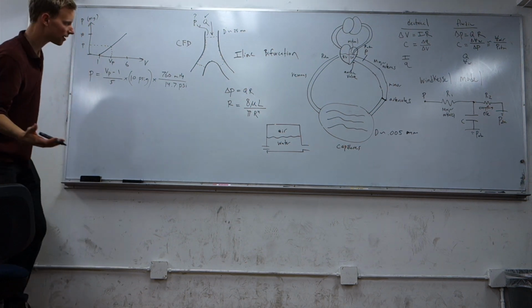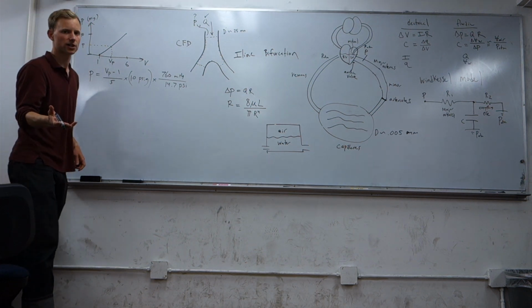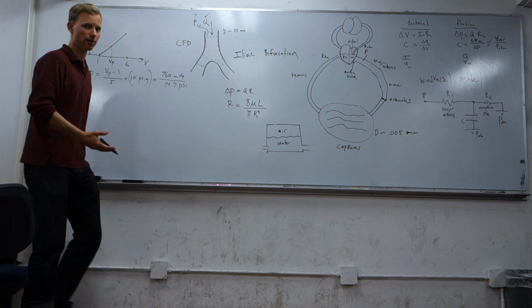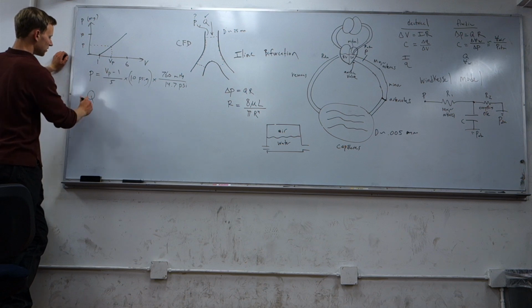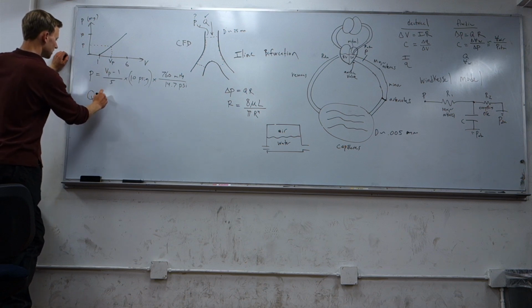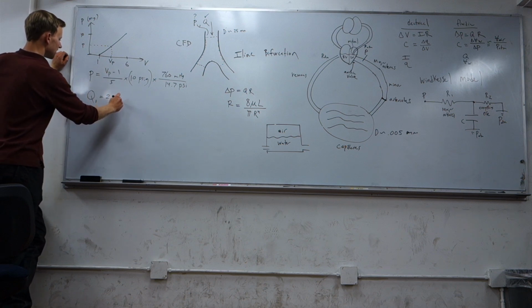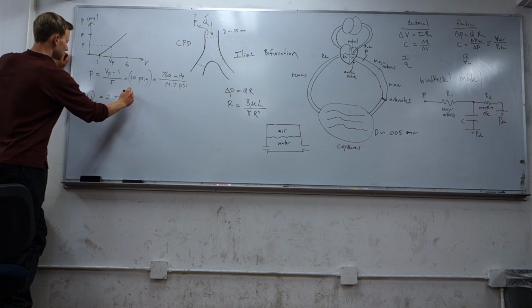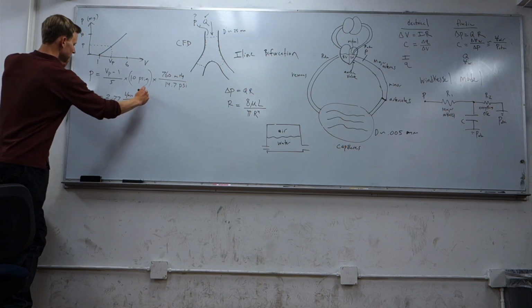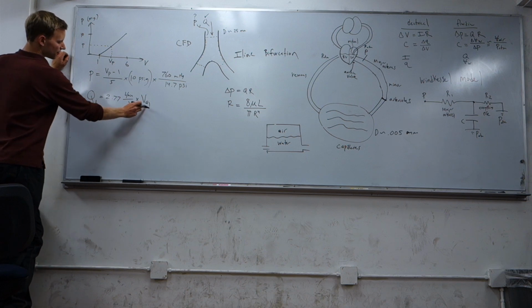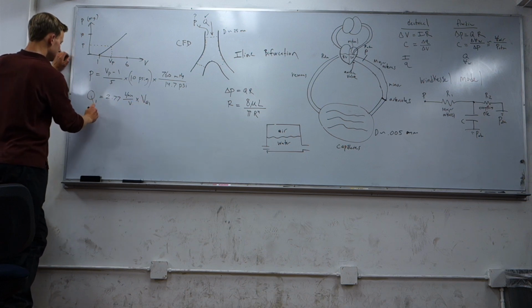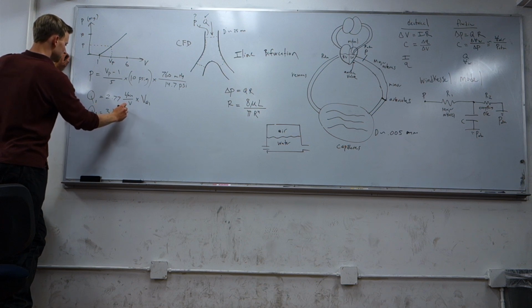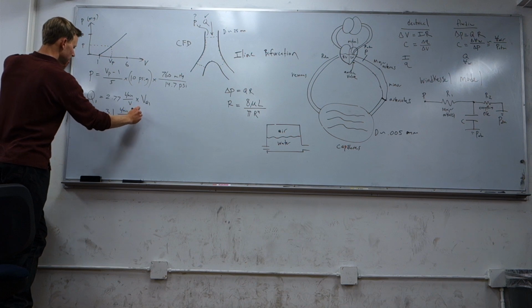Now, the same transfer function, or an equivalent transfer function, needs to be written for the flow sensors. That is easier because the flow sensors don't have an offset at 1 volt. So Q1 is equal to 2.77 liters per minute per volt times our VQ1, if this is the value on the oscilloscope that corresponds to the Q1 sensor. And then Q3 equals 3.1 liters per minute per volt times VQ3.